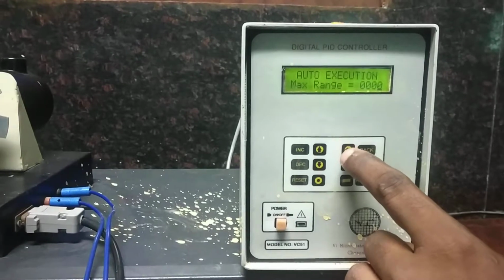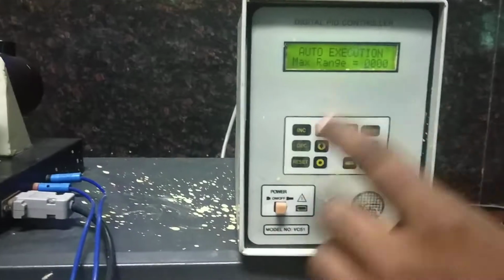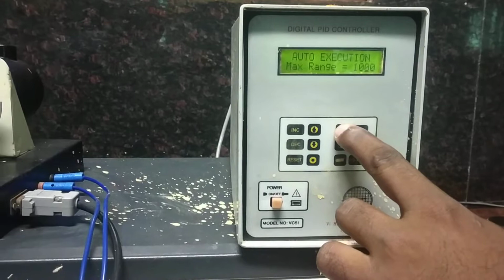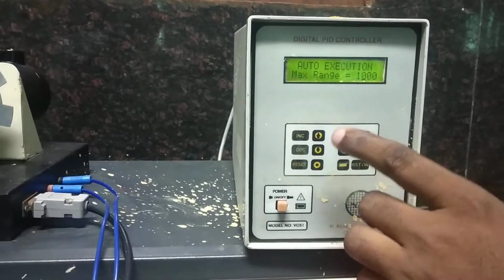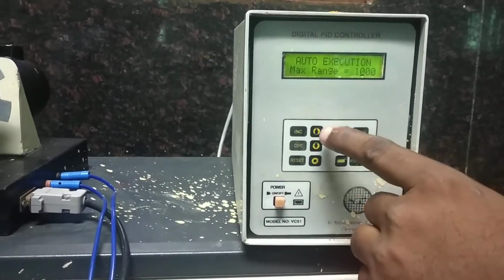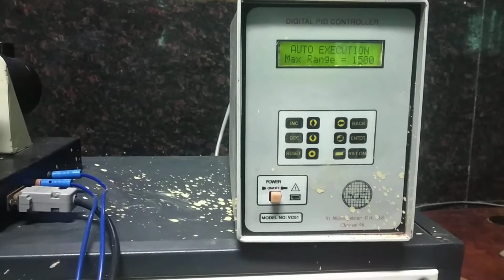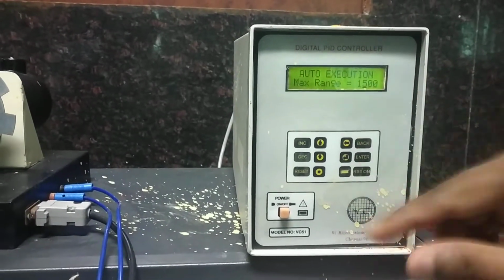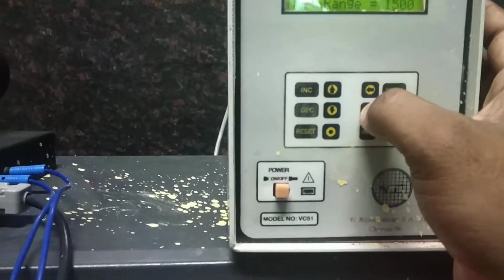By using our back button, press this back button. Now the cursor has reached this location. There you increase the value from 0 to 1. Again press the back button like this. Now the cursor is at this location. Here raise this value up to 5, by means of using this button, from 0 to 5. Now this is the maximum capacity of the motor. After typing this value, just press enter by using this button.